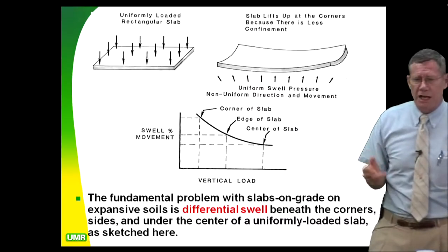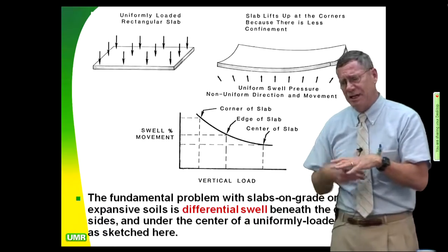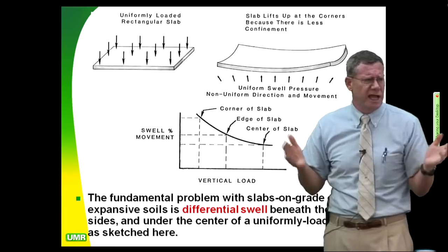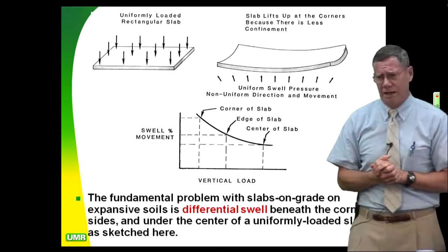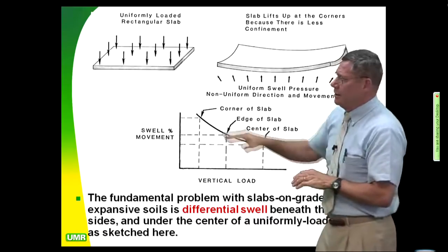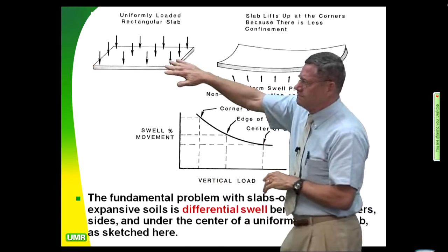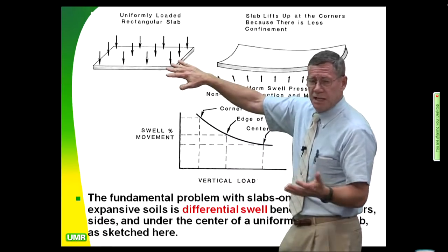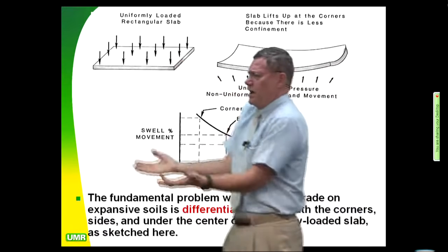This building had a huge monster slab on it, 12-inch slab, double reinforcement, number 8s at 6, 2 layers. Should have been able to withstand B-52 bombing raids. Slab was breaking up like crazy. Why? You can't have uniform resistance to soil heave. The guy that designed that slab designed it for all these forklifts running around carrying paint.